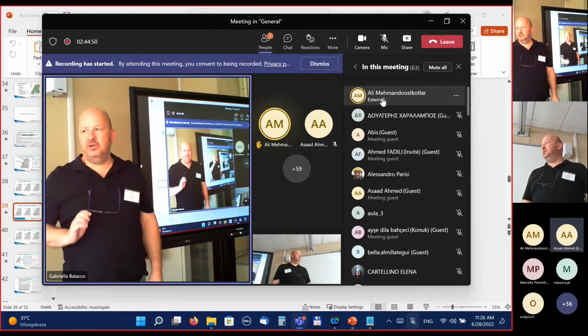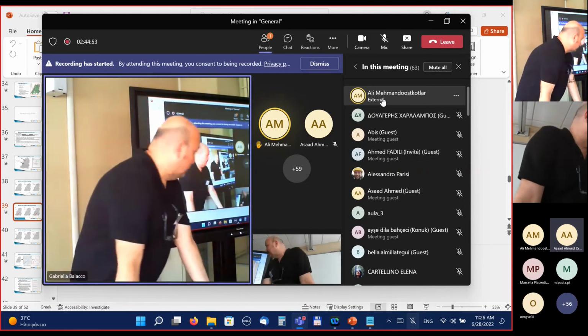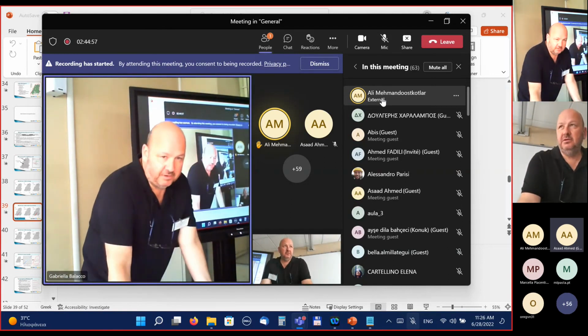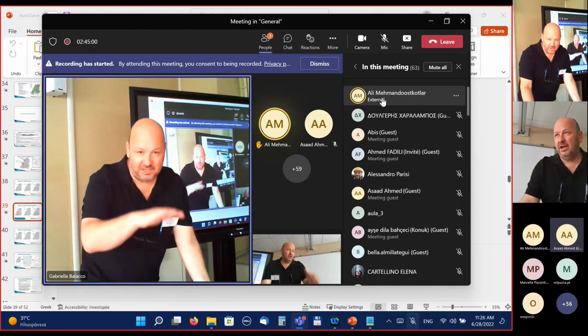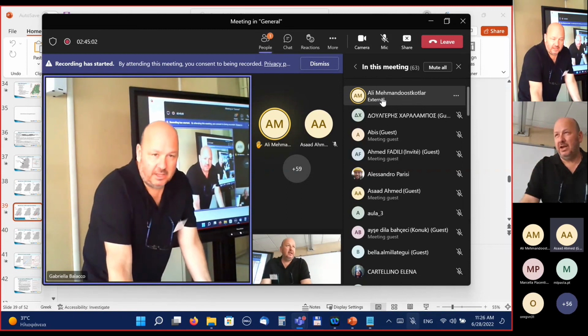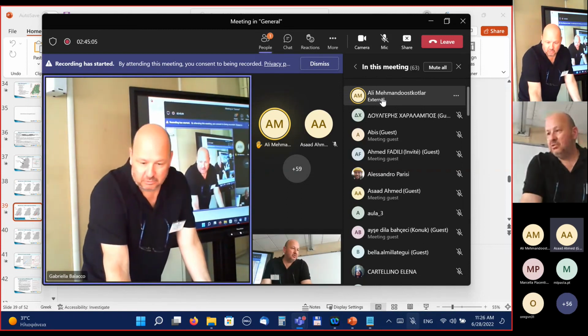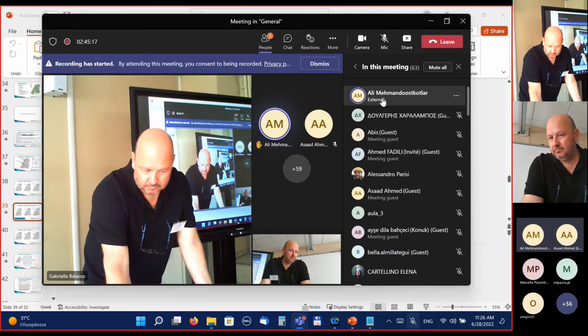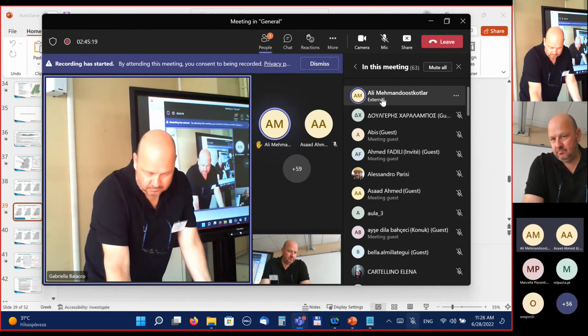One boundary condition is the precipitation that goes to the top of the soil. And the bottom boundary condition would be the recharge, which is going to be used in the groundwater model. But if the phreatic water level comes near the surface of the soil, then we have to use that as a boundary condition too, or it should be the answer of the groundwater model.